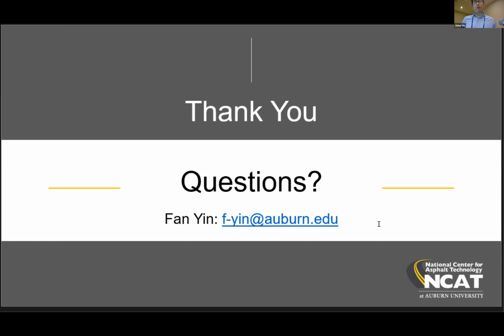Yeah, that's a question that we started to look into more and more because of the sustainability focus of our community. I think at this point, agencies, at least from the asphalt application perspective, have not thought about the recyclability of those materials as they get further aged. Personally, I think there will be a limit to the stiffness or the rheological property of the RAP, beyond which we really need to deal with that material a little bit differently than what we are doing right now.